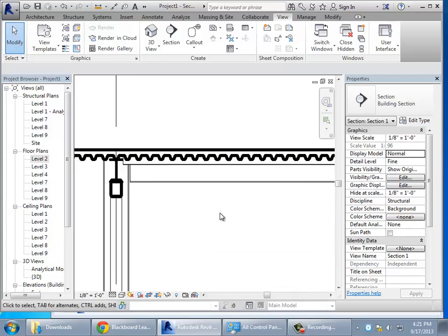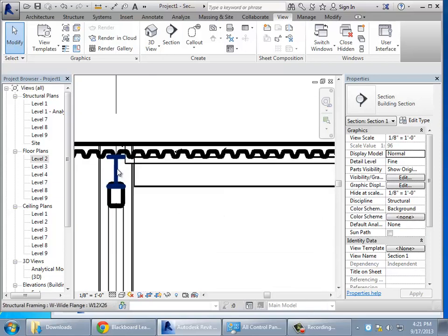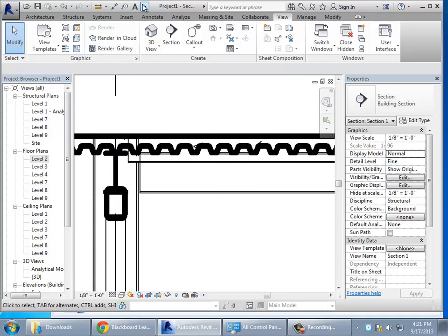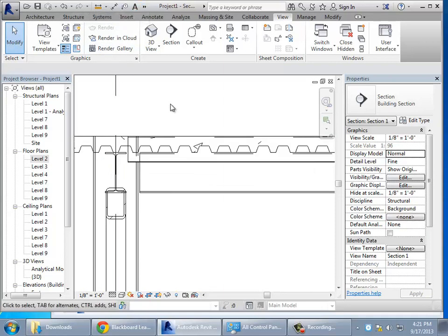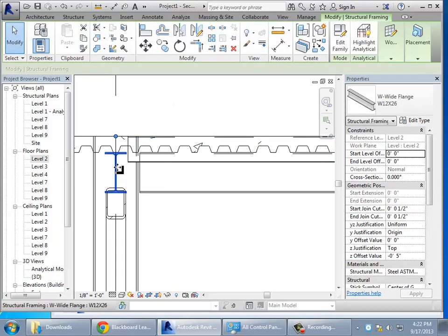So you can actually start to see now that what you're getting into is, I'll even turn down the line weights. We really are starting to get beams, the concrete decking running right on top of them. Have the level of detail you want. You're using your model and actually create all the construction details out of it. So it really is worthwhile spending the time to go ahead and make sure that that beam is 5 inches low, because you do want it to be underneath the deck.